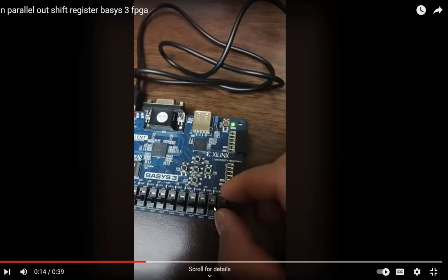Then I use switch 1 as a rising edge to put it in, so it's injected into the shift register. Then I turn off switch 0, give a 0, and provide a rising edge. Just keep doing that for 4 bits, so eventually you're getting 1010 as the data input. At the 4th rising edge, it finishes the 4 bits.